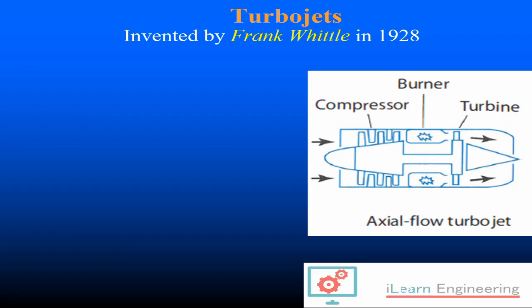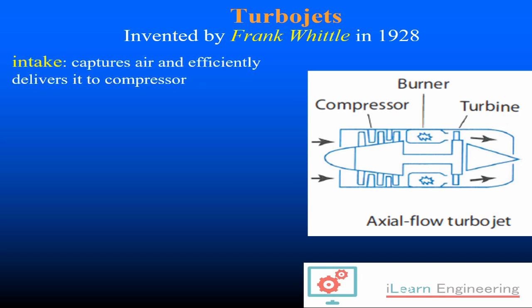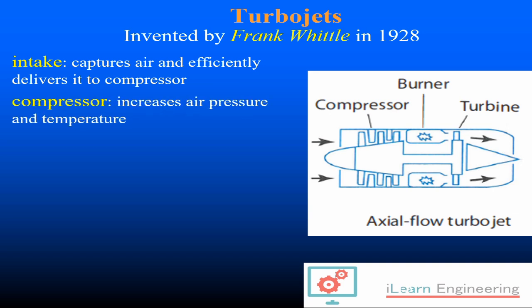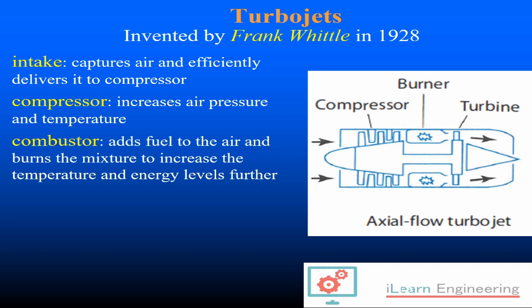So it's interesting that the turbojets were invented by Frank Whittle in the UK in about 1928. What happens is the intake captures the air, very efficiently delivers it to a compressor, which increases the pressure and the temperature of the gas, which then goes through a combustion chamber, which adds fuel to the air, burns it, increases the temperature and energy levels even further.